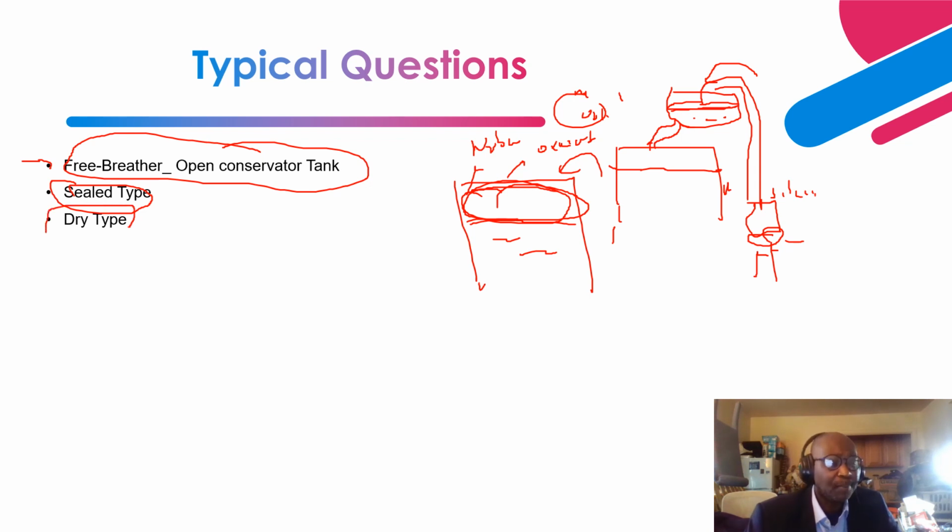Next is a dry type transformer. Okay, so dry type transformers are used mostly in very low voltage and sometimes a little on the medium voltage, up to about 13.8 kV level, and they are progressing to about 34.5 kV for dry type transformers.